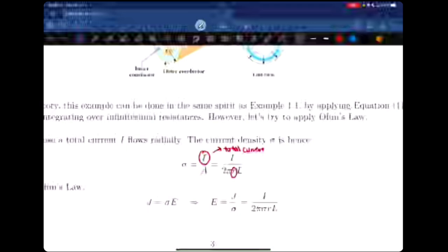Okay. The next part is kind of small, might not come out that frequently, but it's on IV characteristics. So this is basically just a graph of I against V. And of course, for a linear resistor, you expect that it's a straight line passing through the origin. But for non-linear stuff, you can get random curves like this for your IV characteristic. So something like this curve here, you can see that obviously the resistance is not constant. And to evaluate resistance, you want to evaluate V over I at that point.